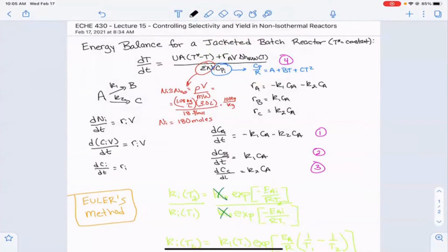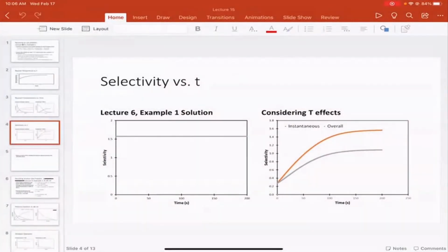But one of the things you could do is that if we have a large solid reactor, well, you know that solids have higher heat capacities than gases and liquids. So you could always just heat the solid. You could get the jacket to warm the reactor itself for some time before the reaction occurs. And then maybe you put that in and you get a little bit of heat transfer immediately from the solid. And then you have to heat up both the solid and the liquid over time. And maybe how you stir the reactor plays a role in that, et cetera. There's a lot of things that we could think about here.